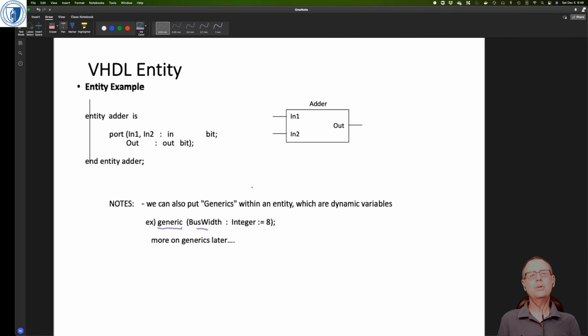So usually what happens, I think in the synthesis, is you can refer to a particular expression as a variable, but when the synthesis actually generates the configuration of the hardware, it moves that expression into whichever signal uses that particular variable. So all of a sudden, the actual variable is not available.